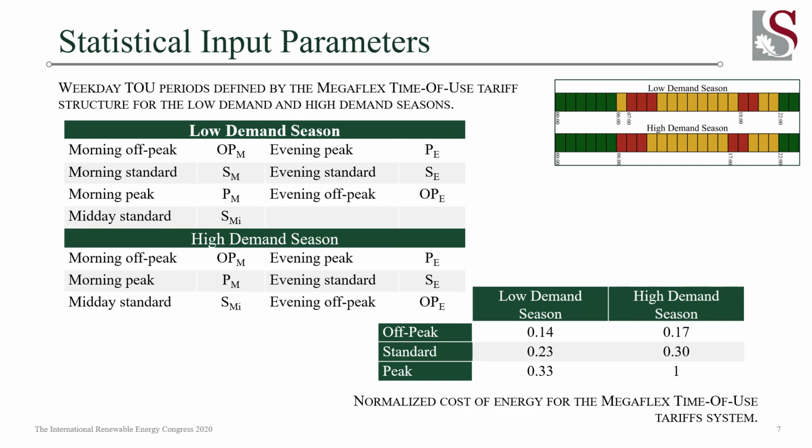So what we're essentially doing when we reduce each of the temporal lines for each of the low demand and high demand time of use periods is reduce these varying temporal profiles to two statistically defined features. This creates an equal weighting for each of the time of use periods. Now, as we saw with the previous time of use tariff structure, the off-peak period, which in this case is not as important to us for siting purposes, is defined over a higher temporal range, whereas the high demand season morning peak and evening peak periods are defined over a much shorter time interval.